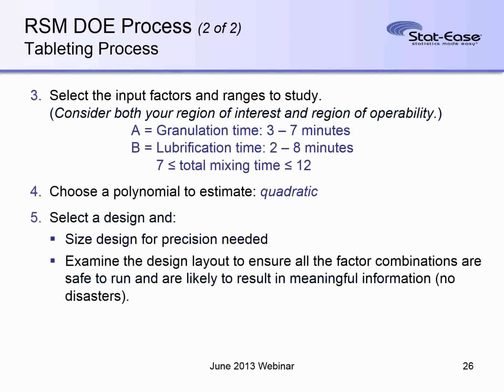You always need to take into account your input factors. Number one, because you're qualifying a process, you want to make sure that you're in a reasonable operating region. Sometimes this involves adding constraints to your process, places where you know it won't work. Sometimes you just need to limit your ultimate ranges of the factor settings. It also requires that you have a reasonably good estimate of what model should fit the true response surface. Again, this is determined through subject matter knowledge more so than anything else. Previous experiments on the subject are a good source for how to determine what the true model is.